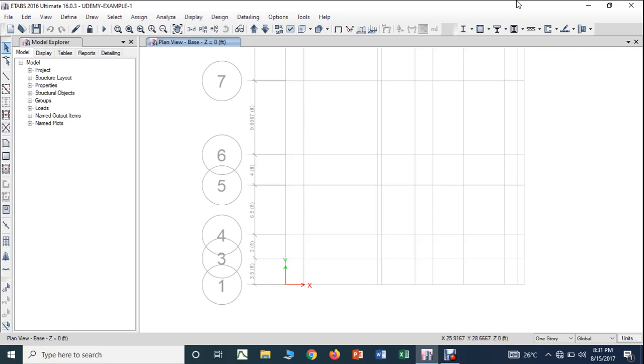So you came to know that the material I am going to use is steel, which we use as rebar, whose strength will be 415 Newton per mm square, called the characteristic strength. Similarly, another most important material that we need here is concrete. How do we decide the concrete? The concrete is decided based on the grade of concrete.